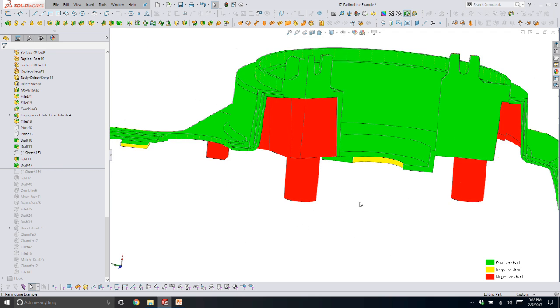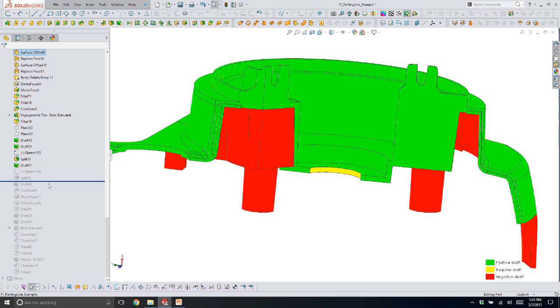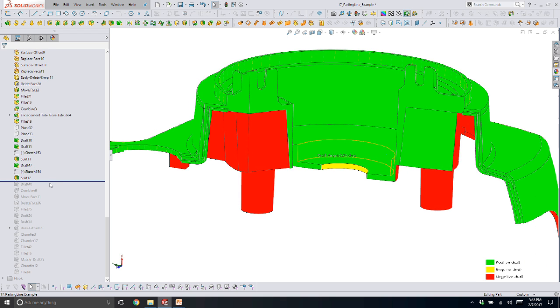So I was really easily able to jog my parting line. Just remember that split. If you ever need to do any kind of parting line, or you've got a little tab that the parting line wants to jog down to build that tab, split it along the intended parting line, add the draft, put it back together, and combine.